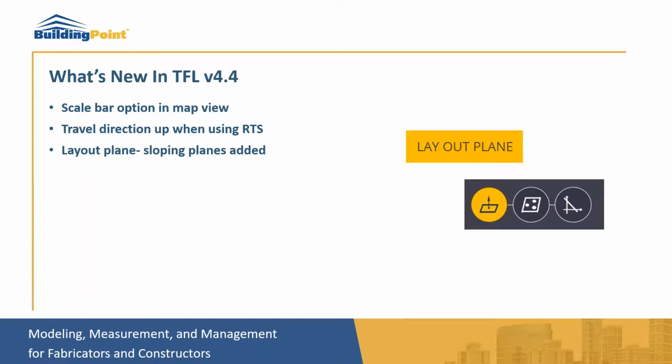And the last option, another easy way to key in a sloping plane, is by selecting the point that you want the plane to start. Then a second point, to define the direction of this plane, and then you can key in the slope either using percentage or run rise values. And again, this sloping plane would extend to the entire job, not only in a certain area, but cover the entire job.